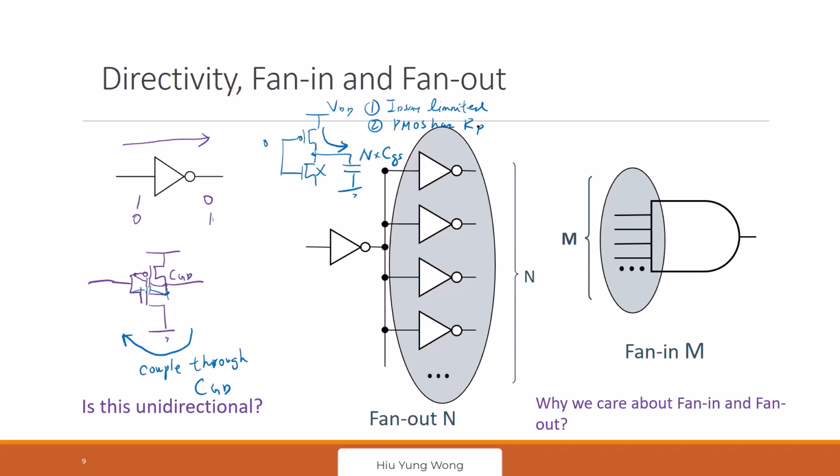So I was trying to fish for this answer, RC delay, but your classmate is even better. He thought about, even if you don't have RC delay, my transistor has a limited driving capability, right? You won't see this by this symbol, right? We always work on this symbol, but we need to think deeper.